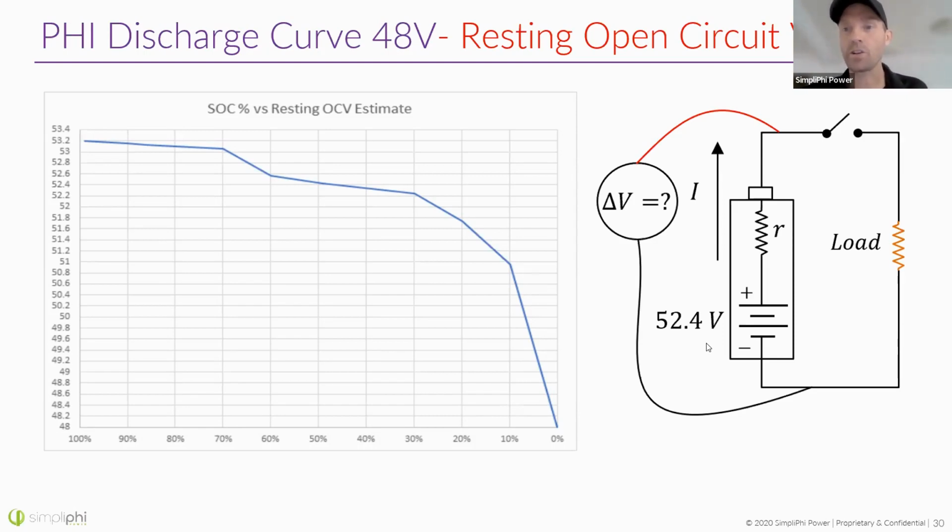Jorge asks, are there any integration guides for NG? Do we have any for Enphase microinverters? I think the IQ8s, the latest Enphase release, prevent communication with some charging equipment. And so if you're using an Enphase IQ8 microinverter, I would recommend you stick with Enphase batteries because they pair well with the IQ8s. Enphase is trying to be exclusive in a way, kind of like Apple, right? So we do have integration guides, I think, for SolarEdge inverters. So check our website for that.